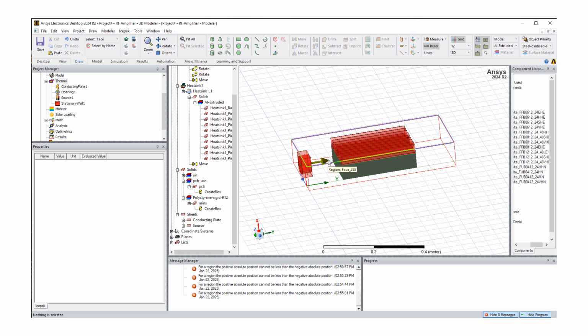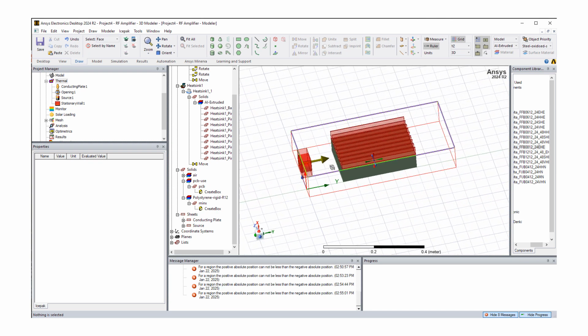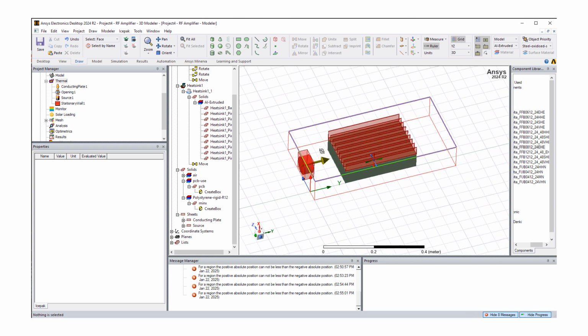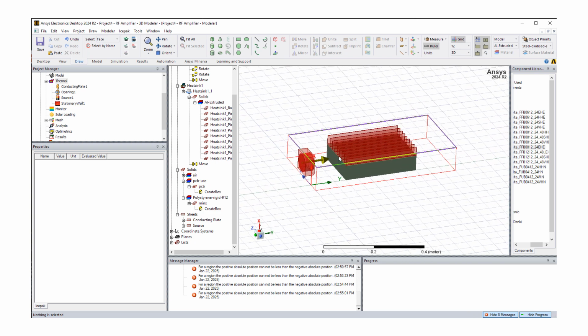And then we're going to submit our job, execute it, make sure the flow is converged, and then we're going to look at the solutions to see where the hot spots are. If the solution makes sense, we're going to look at the flow field, and we're going to do that using AEDT Icepak post-processing capabilities.